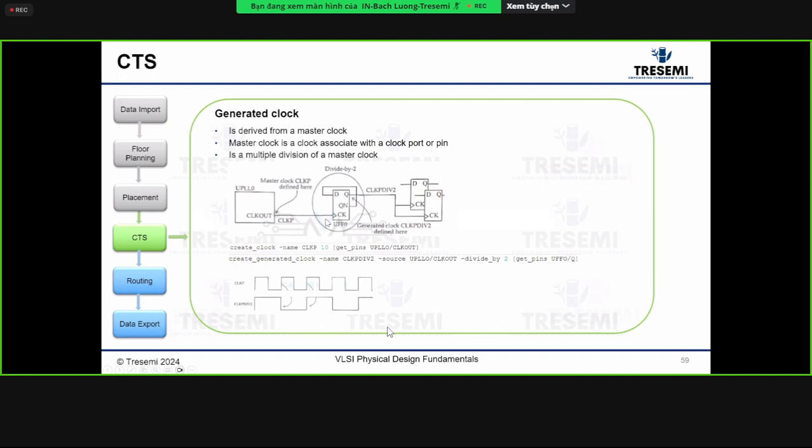Those are the 2 things that we talked about, the non-stop pins. It automatically traverses through here if you don't define a generated clock. But if you define it, it will stop here because this becomes the source of another clock. That was part of the definition of a stop pin and non-stop pin. So thanks, Tim. Yeah, it was covered in the last lecture. I appreciate you bringing that up.